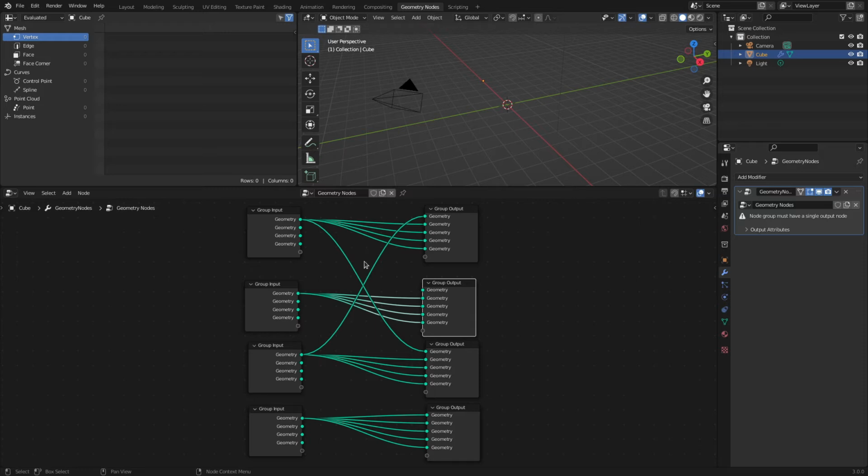Now this is cool. This is muting links. How you do this is holding Control and Alt down at the same time. Control Alt, got them down. Now I'm going to hold my right mouse button down, not my left mouse button, my right mouse button. And I'm going to drag it across the link I want to mute. So right mouse button down, drag it across. You see that little line? That's going to mute that particular link, like that.